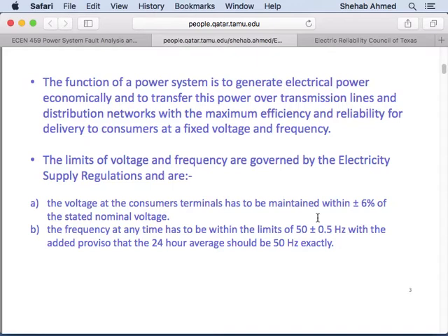Power transmission. The benefit of AC is that we have a transformer, because AC quantities can be stepped up or stepped down with a transformer, and we need transformers to be able to control losses when we are transmitting power over longer distances, right?